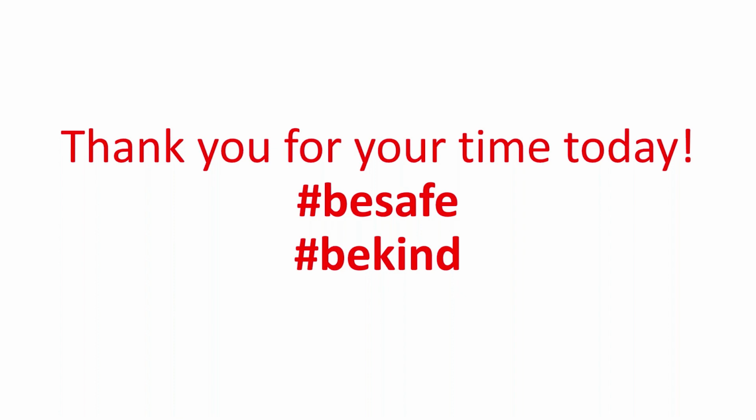And the technology there, again, you've got a very similar interface when you're drafting, things like your crossing selections, your window selections, your right-click functionality, your object snaps, everything's the same. The only difference in the web app is it uses the simplex font when you place text, and that's to provide optimum functionality within a browser. Because if you had all those different fonts to think about, the browser would have to think about that, and it would slow the AutoCAD web app down. But it's a great piece of functionality.